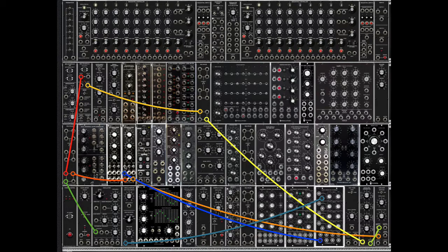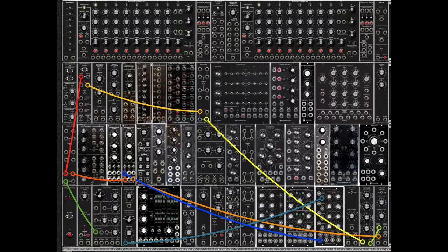Once you do this, have the switch in linear, turn this all the way up and leave this all the way up, because now this initial gain will act the same as that, and any signal you bring into the control input will act as your hand on that knob. Now take another version of your gate output and bring it into the Moon 511. Take the output of that into the control input.